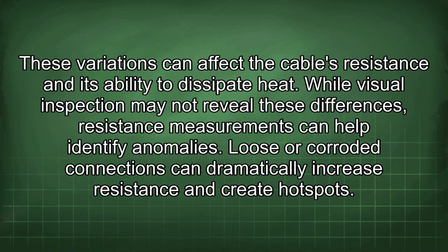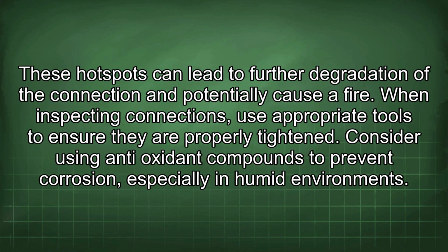Loose or corroded connections can dramatically increase resistance and create hotspots. These hotspots can lead to further degradation of the connection and potentially cause a fire.